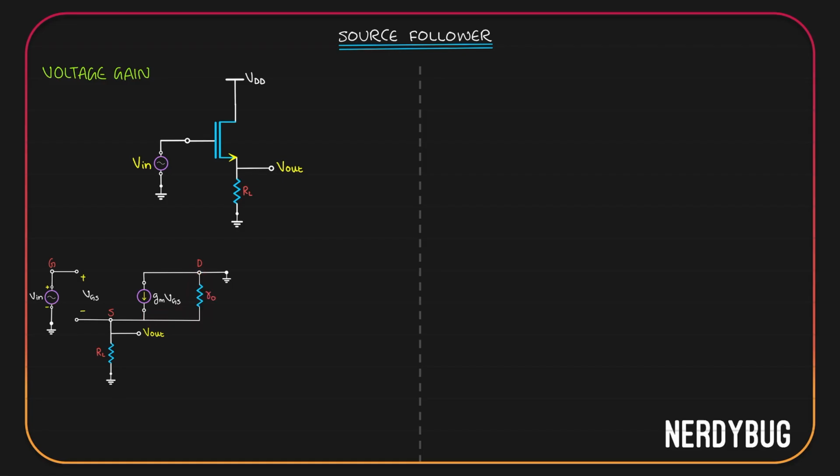Let's make this more simple. You can see that RL is between the source and the ground. How about R0? R0 is also between the source and the ground, which basically means RL and R0 are in parallel with each other. So we can simplify the model like this. All I have done is I took R0 from here and put it over here in parallel with RL, because technically RL and R0 are parallel. I can even replace these two resistors with a single resistor whose resistance is RL parallel to R0.